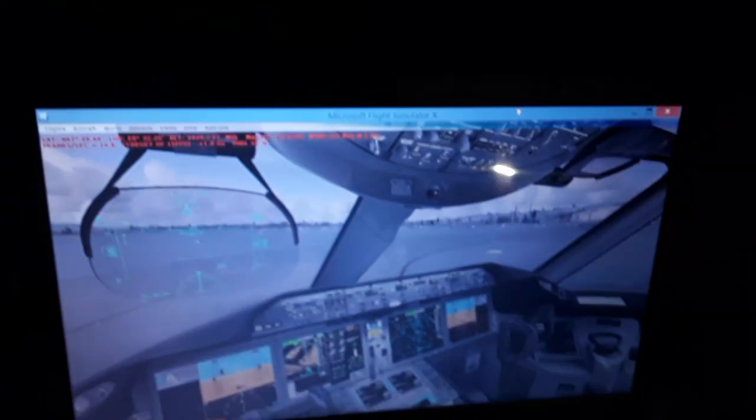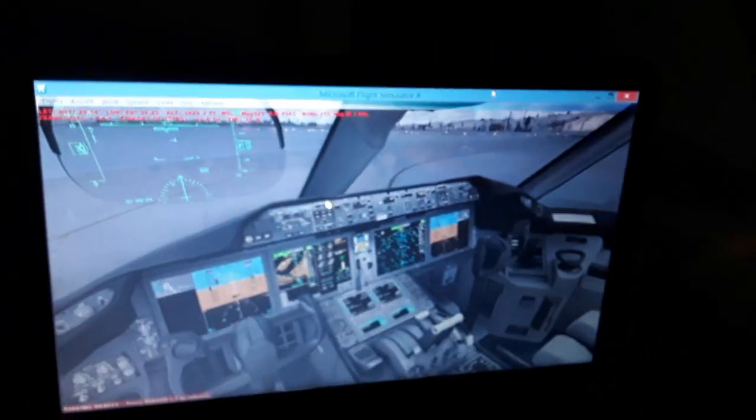We have also the VOR stations and the NDBs, the navigation aids, the navaids, also the waypoints, which are horizontal and vertical navigation fixes with altitude and speed constraints. The waypoints, we're going to select some from the flight management computer later, one by one. They're going to be connected with the purple line you see over here. So we have the flight management computer.